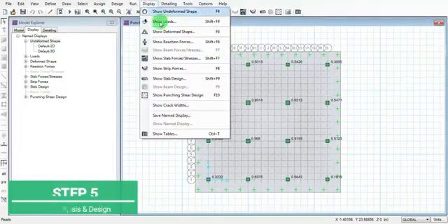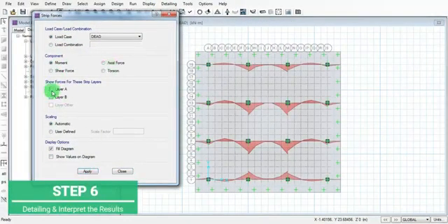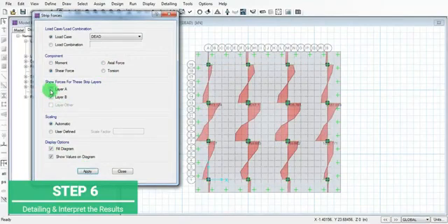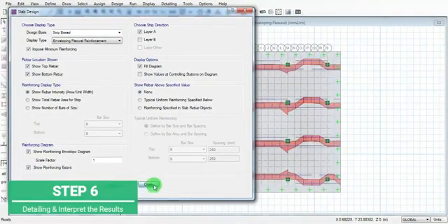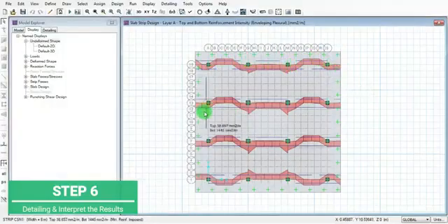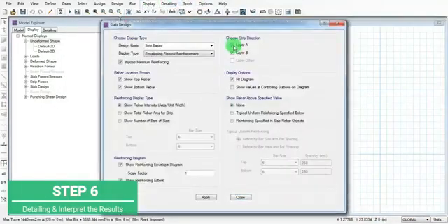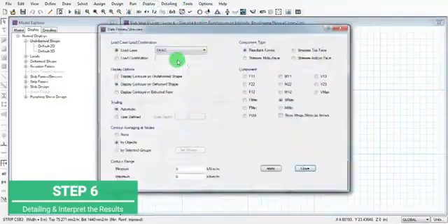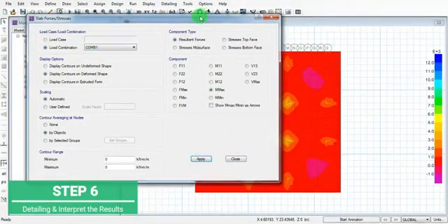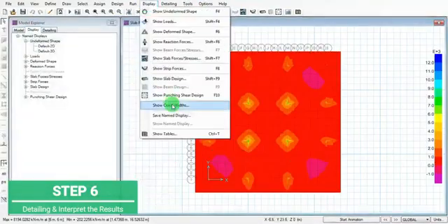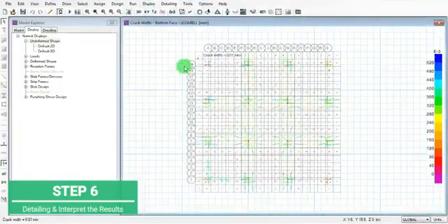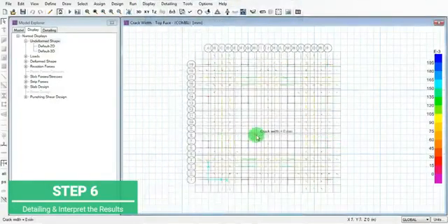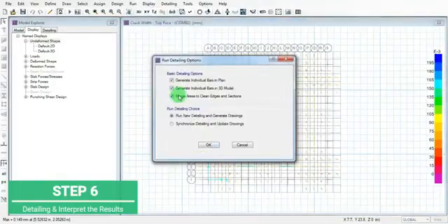Now the next part is to view in detail the different load combinations. Before that, the strip forces in layer A and B. Now get the required reinforcement. Now similarly in layer B for the load combination. This is the crack width values for the top and slab bottom. These are minor cracks. Then start the detailing option.